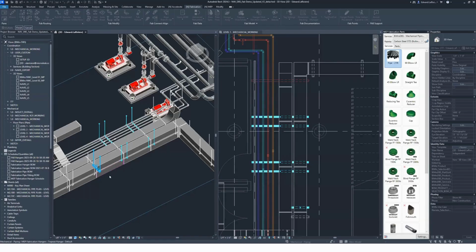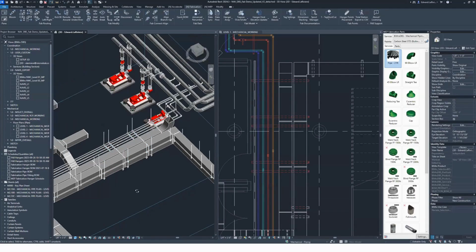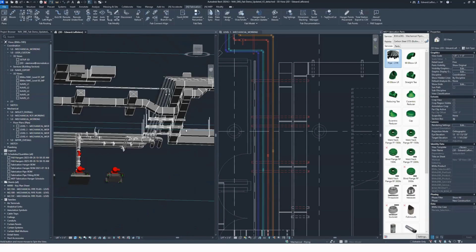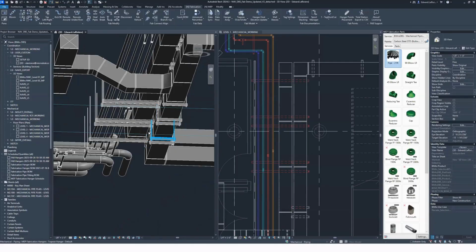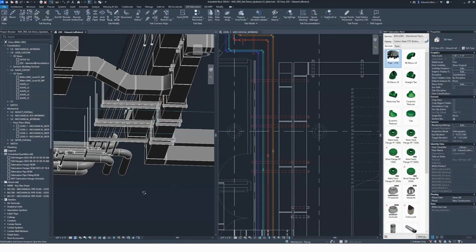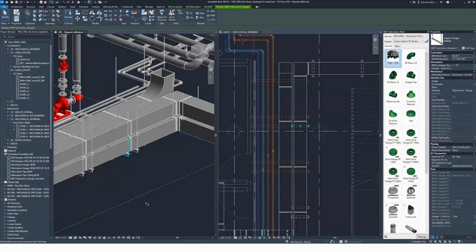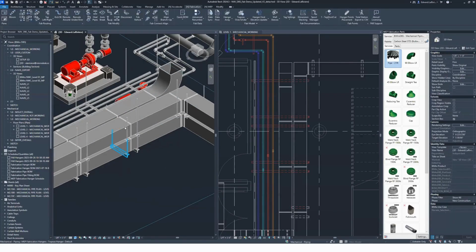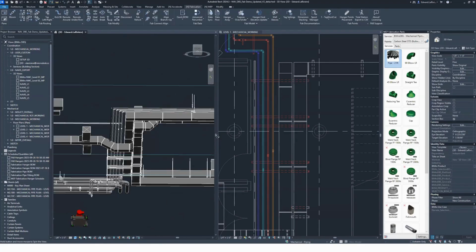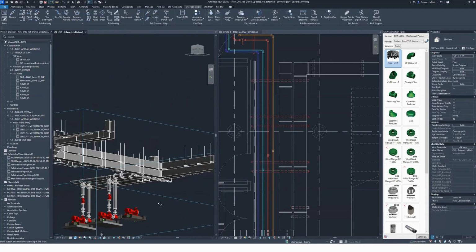Maybe some of them have not. And why don't we let Naviate just jump through here, place down that lower rack for me, and understand that it's only hanging those elements and that those rods actually end at the element above. So we're not going to give you a bunch of rods going all the way through to the ceiling above. We're just going to give you that lower rack ready to go, nice and easy.